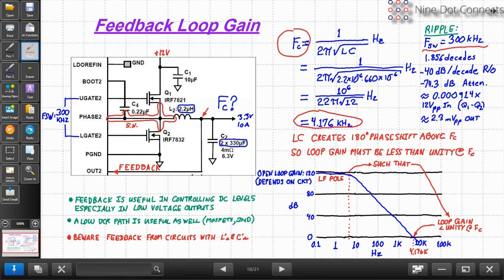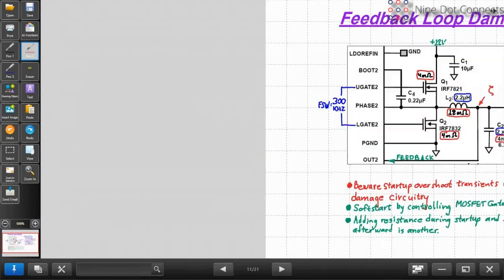You may need to go through an entire additional stage and make a higher voltage coming in, filter it again, and then throw it through a linear regulator or something to accomplish your needs. But for the most part, a lot of things can run off of switching power, and switching power has inherently in it some noise. So that's what we're trying to talk to today.